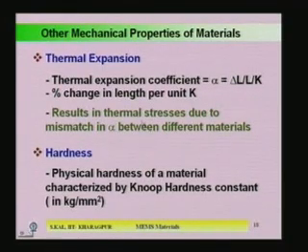So, you see, thermal stress: the earlier stresses we discussed were mechanical stress, where we apply a certain mechanical force and as a result strain is developed inside the material. Another stress is also there, that is the thermal stress. If in a sensor you are not using only a single material, but different kinds of material, semiconductor, ceramic, metals and so on, then all the materials will not have the same thermal expansion coefficient.